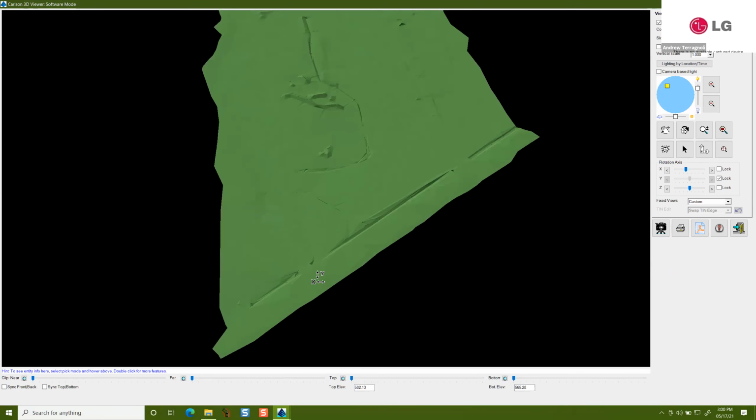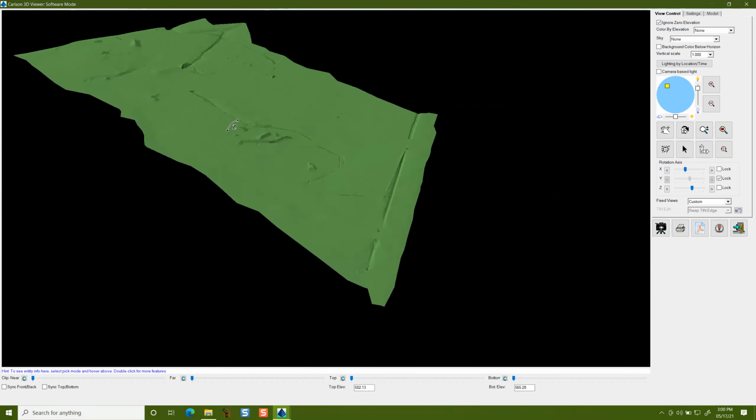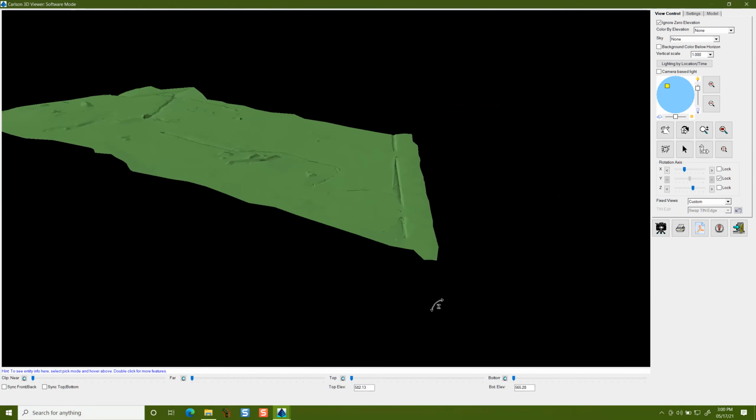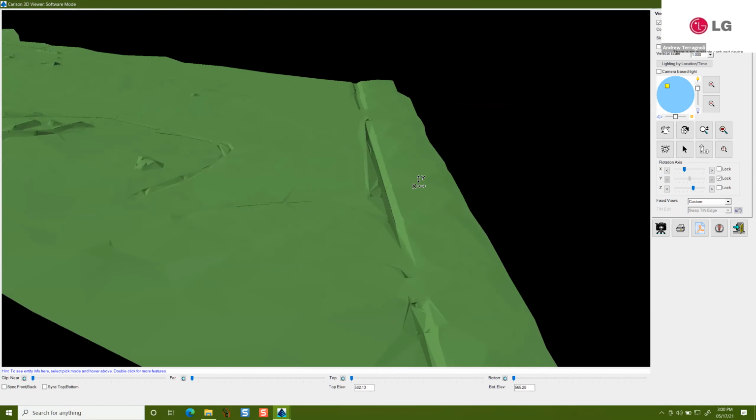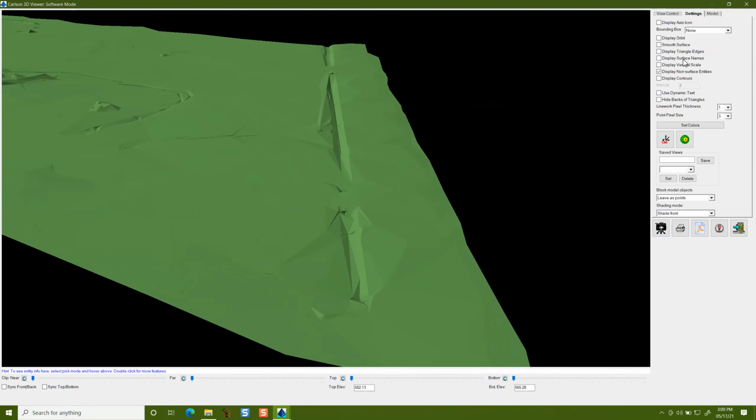Here is, and it could be said maybe that's the roadside ditch, and maybe that's done well enough. But you see these big flat looking triangles across there. There is a driveway there, but still, the road was poorly defined. You usually shoot a center line, every 20 feet. I don't care if you shoot it once down here and once down here if it's mostly flat, but you connect those two points up and say that the center of the road is a break line.